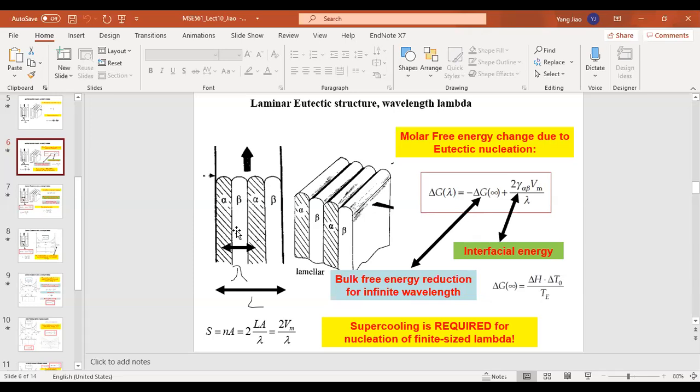So you create a lot of solid-solid interface, and the energy associated with the solid-solid interface is generally much higher than that associated with the liquid-solid interface, because you have to match the lattices, different structures, you have to stretch them and glue them together, etc. All those things are going to increase the energy, or lead to a much higher solid-solid interface energy.